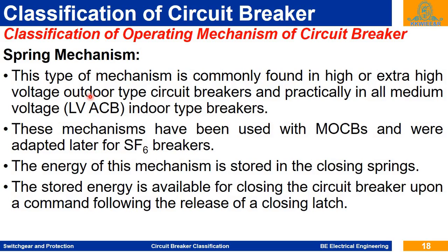Extra high voltage outdoor type, and medium and low voltage indoor type circuit breakers use this spring mechanism. This mechanism has been used with minimum oil circuit breakers, and after that it was also adopted in the SF6 circuit breakers. The energy of this mechanism is stored in the closing spring.